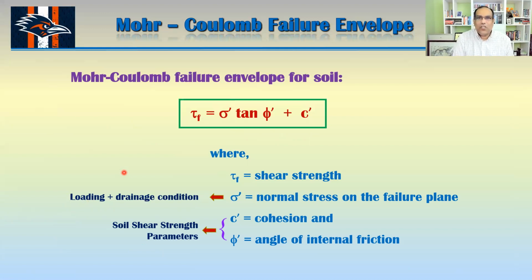On the other hand, if the soil doesn't drain, and you apply a huge loading, actually this loading is not going to the soil, it's just remaining in the water. So your normal stress is not changing, so your shear strength will not change. Okay. So you have to be very careful: it is not only the normal stress, you have to make sure that the effective normal stress changes if you want to change the shear strength.